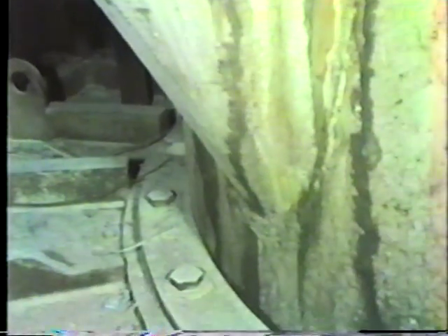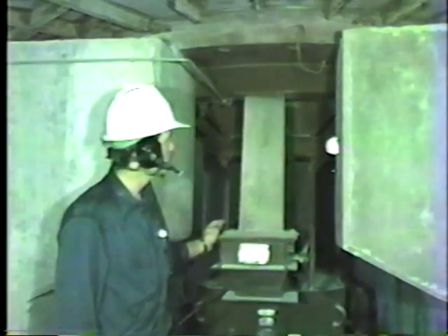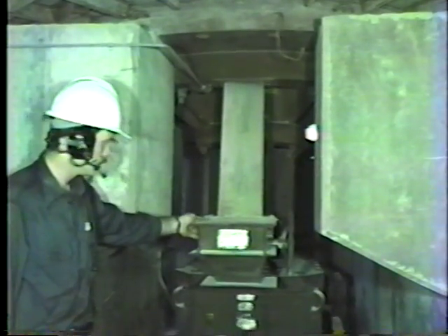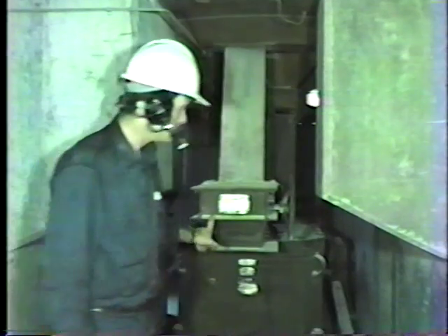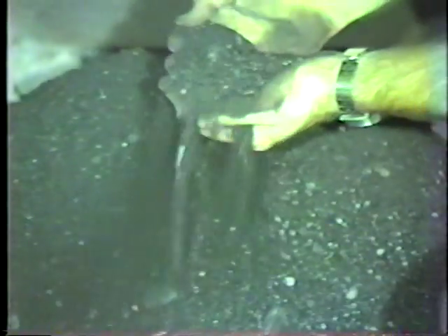You cannot hear the mill in operation. Each Williams DF mill is equipped with a tramp metal throwout. By opening this large gate, removal of tramp metal and hard-to-grind materials is accomplished. This is normally done periodically. Hard-to-grind particles such as iron pyrites, slate, and gravel will accumulate at the bottom of the fluid bed and can be dropped out of the system as needed.